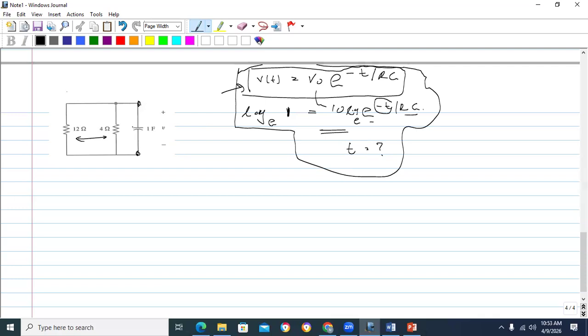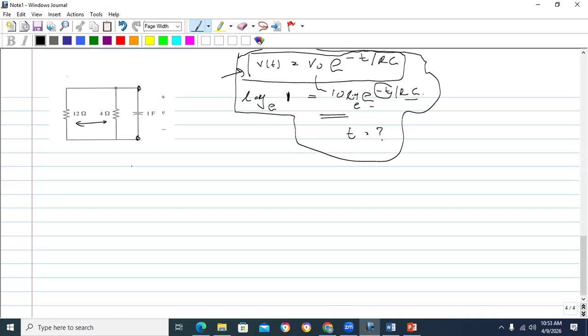differential equation actually here. Okay, so how to get the differential equation? You know that the voltage across the capacitor is VT. Actually, you need to get the equation to find this VT, no? Okay, so if you directly write VT is equal to 1 over C integral of ICT dt, let's say ICT is the current to the capacitor, plus V naught, which is 10. Okay, what is the problem with this one?